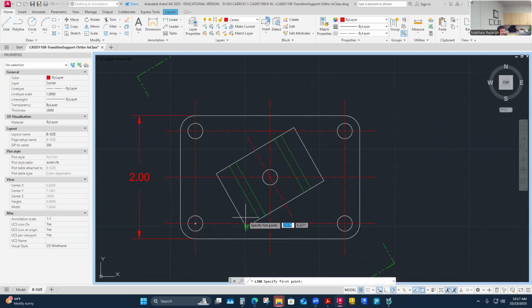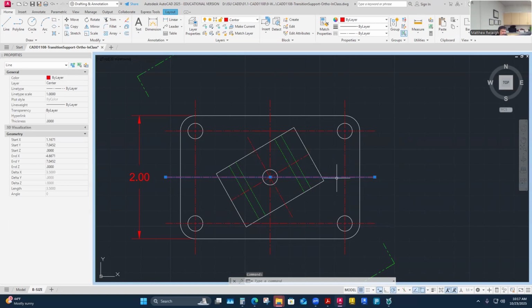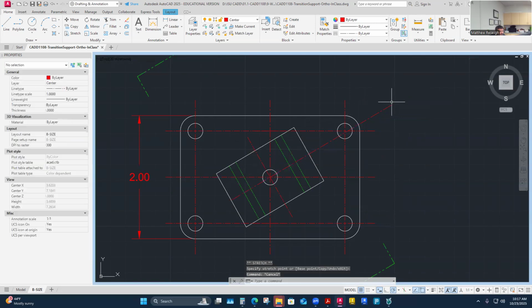It's going to go center line crazy here now, right? Here's a center line between it this way, which makes sense. It's kind of like this is the center line of the hole through it. But if I put this center line through, I can dimension to this maybe and say, hey, this is a nice controlled point. Center lines are good controls. Let's maybe put a degree that is not going to be a reference degree. Maybe it is going to be a critical degree. And in order to do that dimension, this probably has to come out here a ways. I don't know how far, but I want to keep it out in alignment.